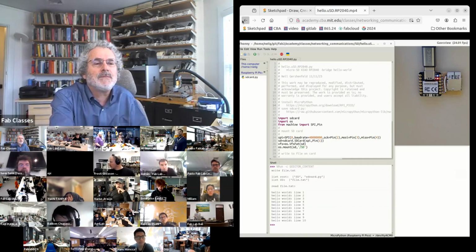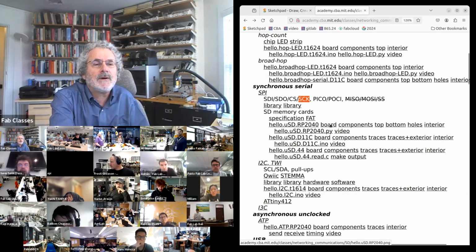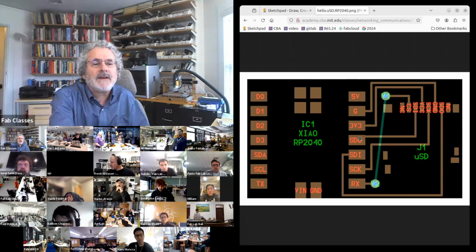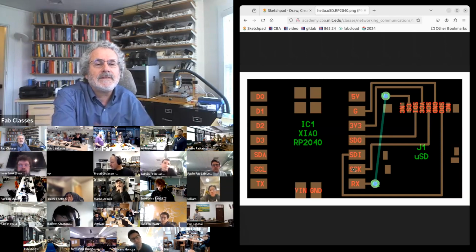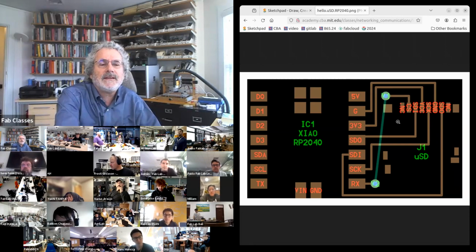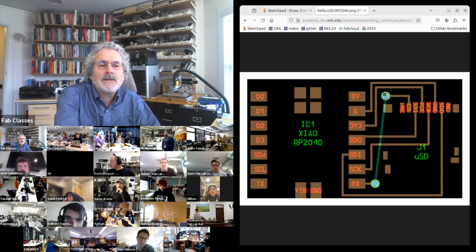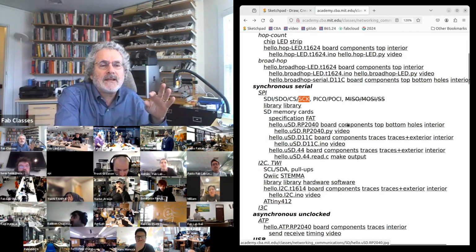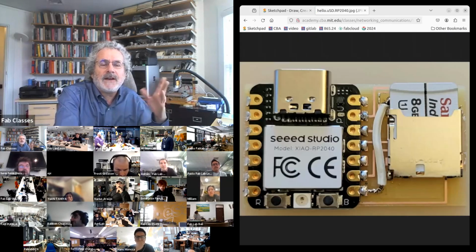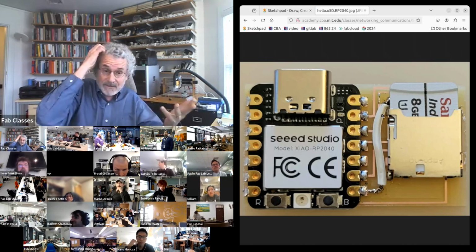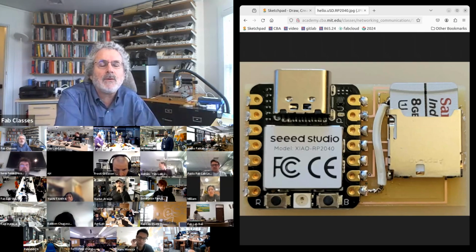So let's look at first the board and then the code. On the board, I've got my lines that I'm using for the SPI data out, data in, and the clock line. Just as an example, this is a board where I could have made a two-sided board, but I couldn't route that from there. But when I'm milling a board, rather than sending it to a board house, if I have just one connection I can't do, rather than flipping it to mill both sides, I'll just run a wire jumper. This is an example of that.